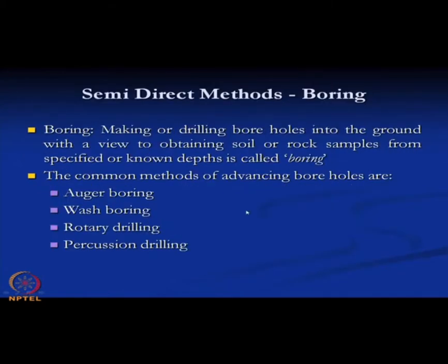Now, semi-direct methods, or boring. Boring is making or drilling boreholes into the ground with a view to obtaining soil or rock samples from a specified or known depth. Common methods of boring are auger boring, wash boring, rotary drilling and percussion drilling.